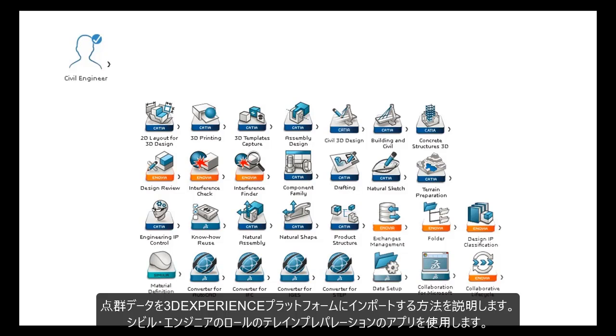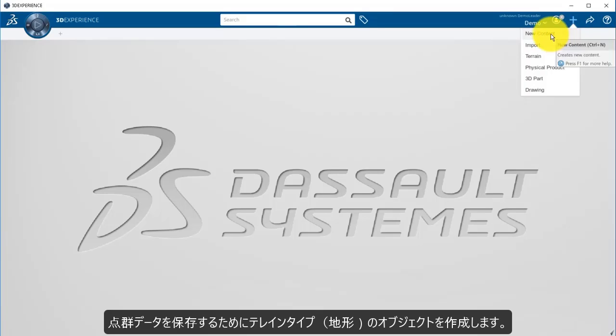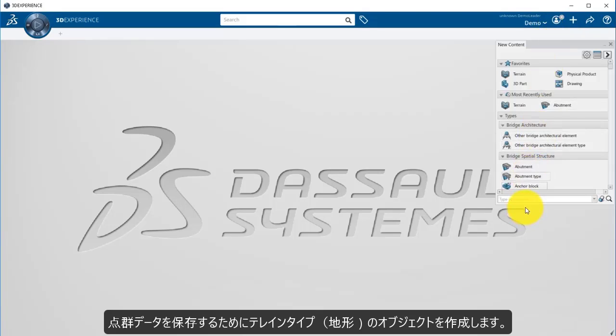In this video, you will see how to import a point cloud inside the 3DEXPERIENCE platform using the Civil Engineer role and the Terrain Preparation app. First of all, we will create an object of terrain type to store the point cloud.